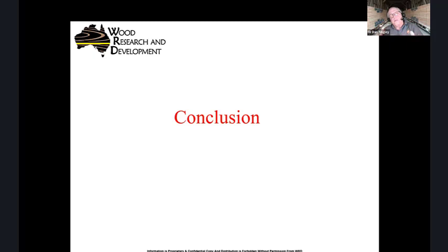The key for me is verticals. I tell my engineering students, do one thing. If you do one thing from hearing me talk today, stop the verticals that originate from the top. I don't care if your deck is not treated, does not have to be treated. If your deck isn't treated, stop verticaling from the top. You'll extend life 3-fold. 3 times.